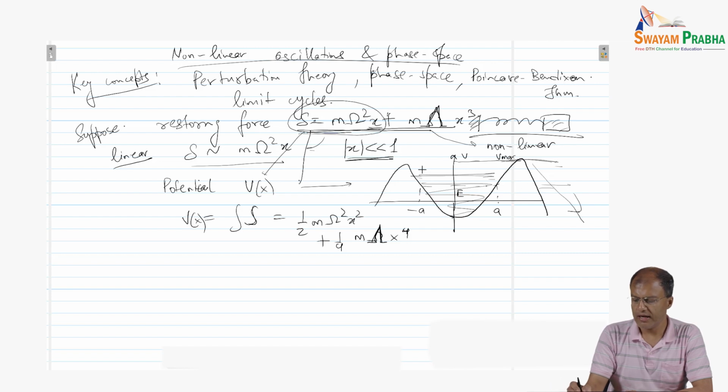If the deflection is small, the spring is going to oscillate, which means we are in the linear regime. If the deflection is large, then we are in the nonlinear regime. Then the spring no longer shows oscillations, it is permanently altered, and we expect the position not to go back to its original position for large deflection because of the nonlinearity.